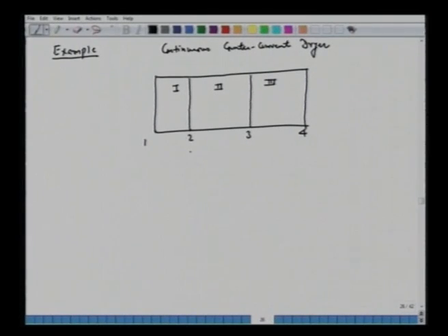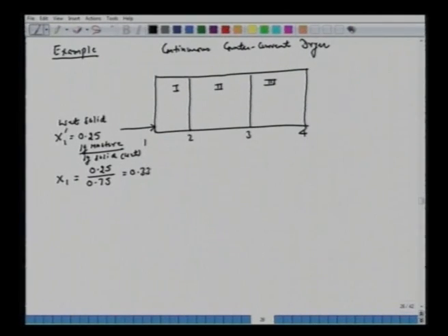So now it reads that solid say enters from one end. It's a wet solid, so it has a moisture content of 25% or 0.25. Now when we say 0.25, this is kg of moisture per kg of solid, wet basis. So for our case we will write it as x prime for the wet basis, so that we can calculate x or x1 for this entrance here as 0.25 over 0.75, equal to 0.333. So the wet solid enters with the moisture content, dry basis, at 0.333, right.